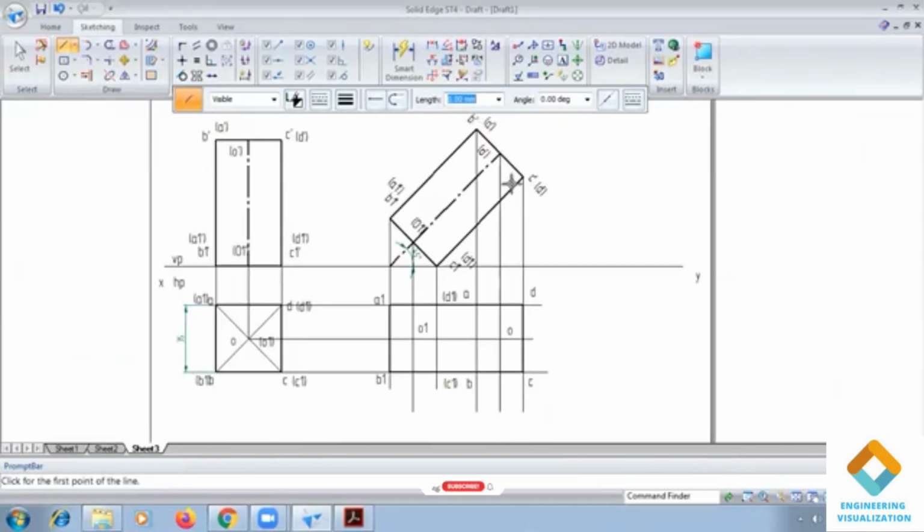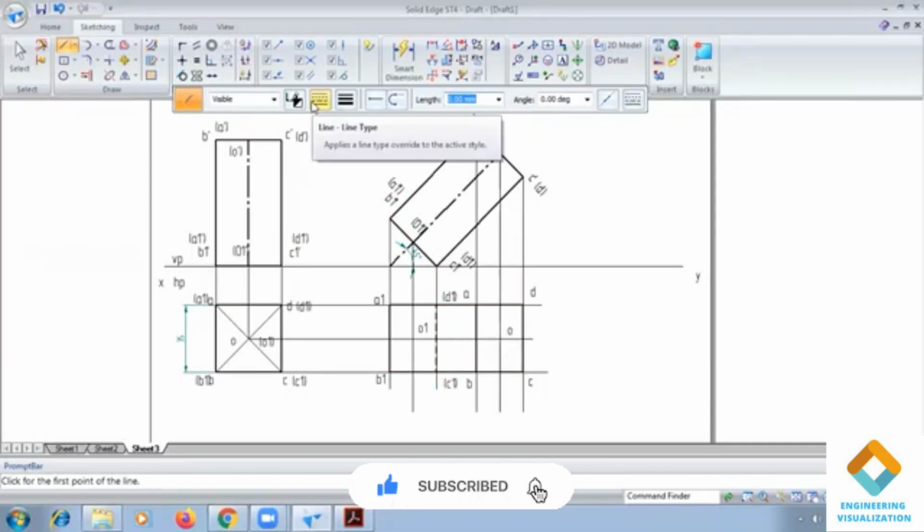Now the visible face. This square face is visible from the top view, that is ABCD is visible. Then this B dash, E dash, and B1 dash, A1 dash are also visible, already in the rectangle. The bottom face is not visible from the top view, so we can draw that part with a dashed line. Then finally we have an axis. So we can show the axis from A1 to O.